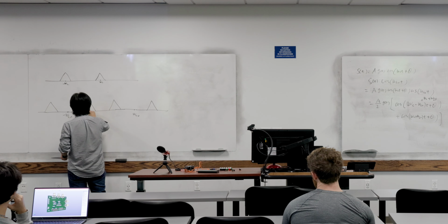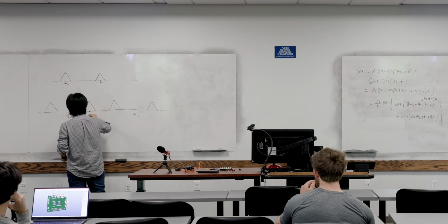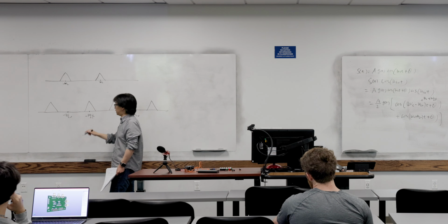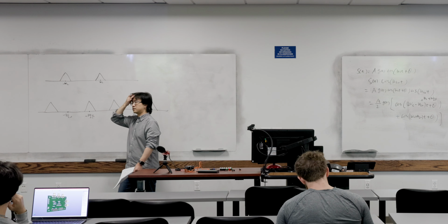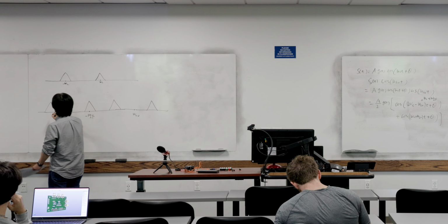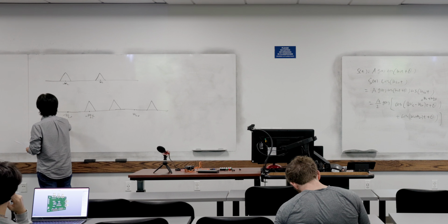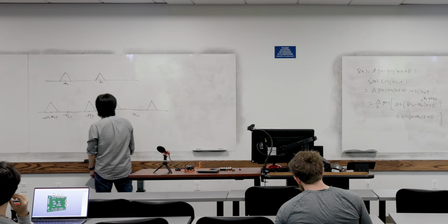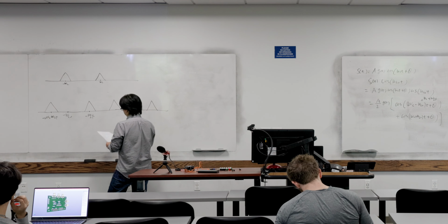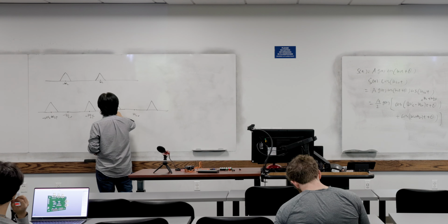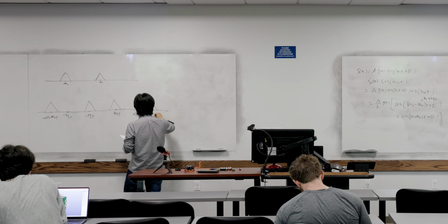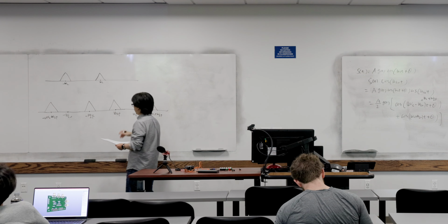And now what we want is basically this part, which is around the intermediate frequency. And the frequency component here is minus 2 omega c minus omega IF, so this part can be filtered out. For this part, that's omega IF. And this part is 2 times omega c plus omega IF. Okay, very good.